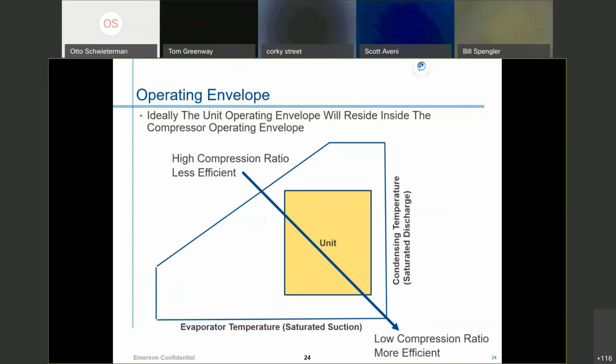Say the OEM says, hey, I want to be as efficient as I can. So rather than that 42-degree farther left, higher compression ratio, they're going to use a larger evaporator coil and use 49-degree water or refrigerant to supply that same 55-degree supply air to the space.